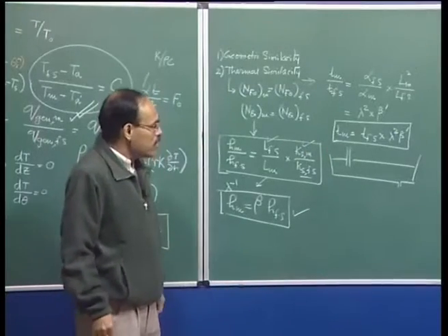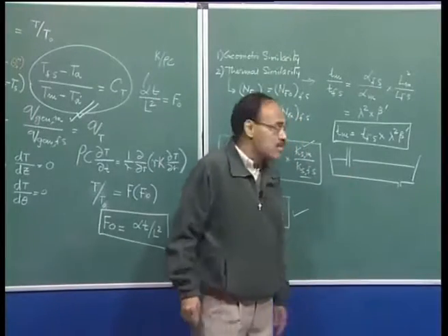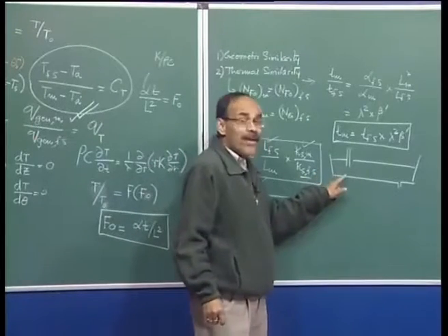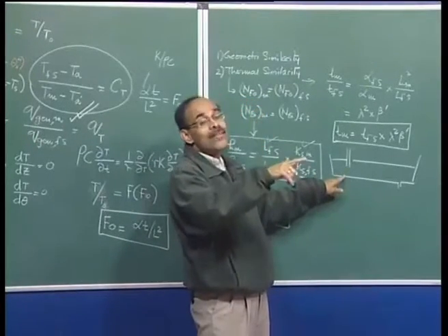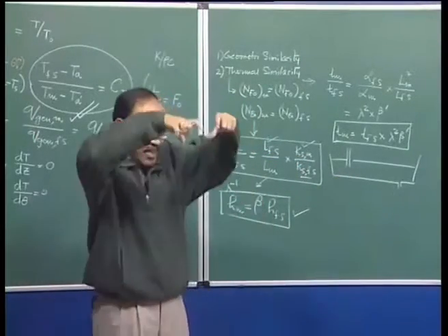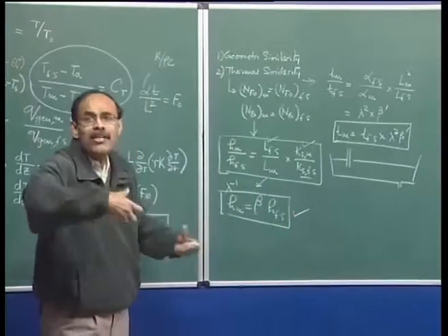Now, in this case, although I can scale down on the basis of the governing equations, get the numbers and maintain the equivalence, it will be very difficult for me to maintain the equality which will come out on the basis of the boundary conditions. Because you can imagine that if you have 1600 degree molten metal in a vessel, a tun dish, you have some finite amount of heat loss.